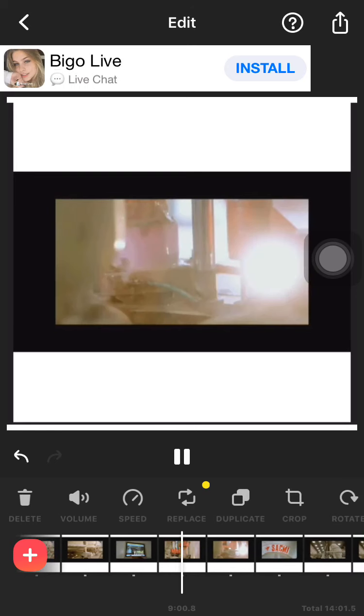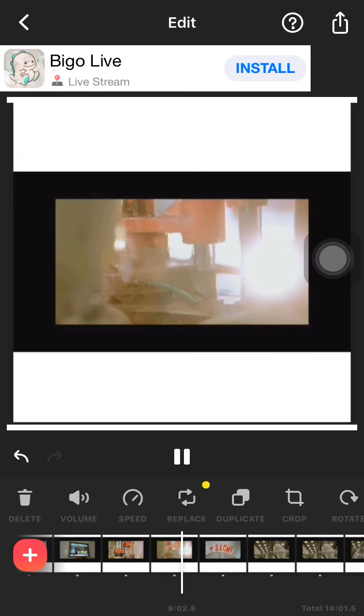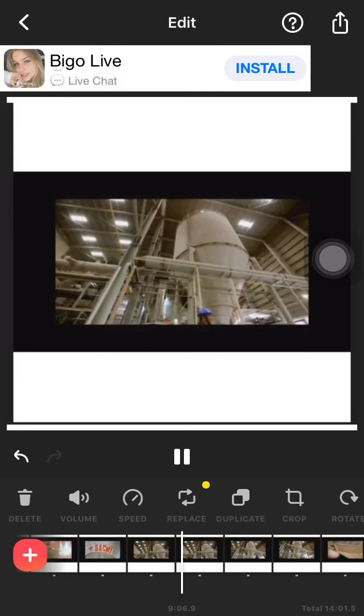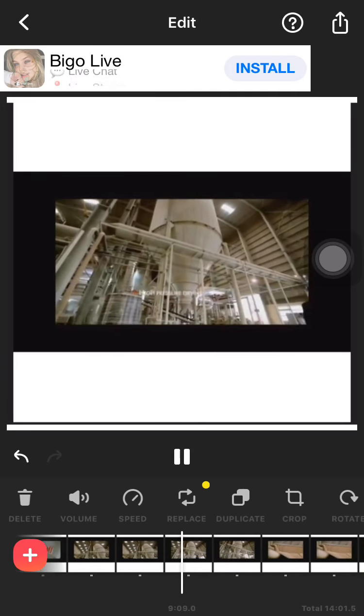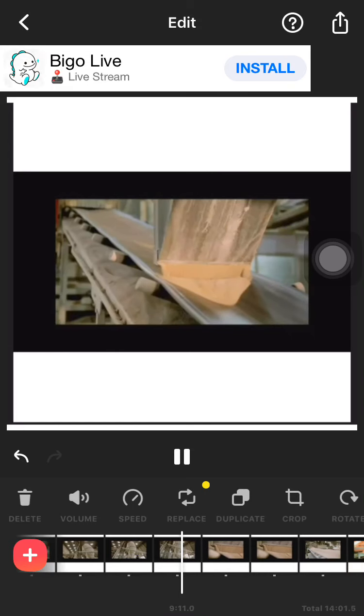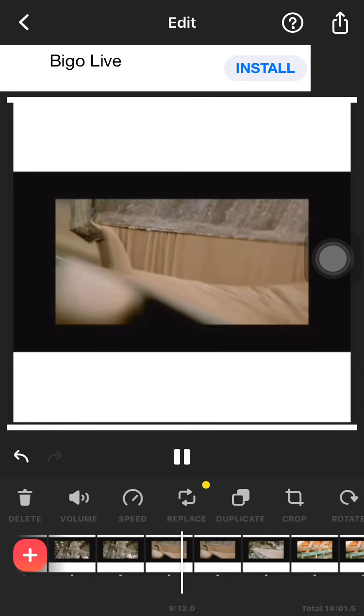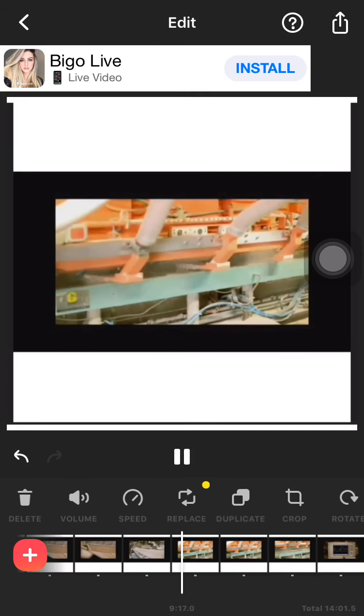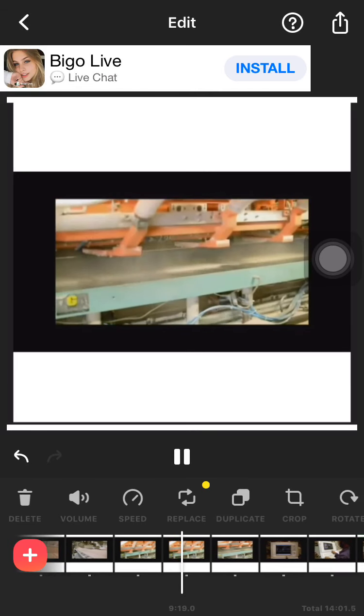The slurry is pumped at high pressure through a spray nozzle. A blast of hot air passed through the spray reduces the moisture content from 33% to 6%, resulting in a fine powder, easy to mold and shape. This moist powder is now ready to be pressed and take tile form at the tile press.